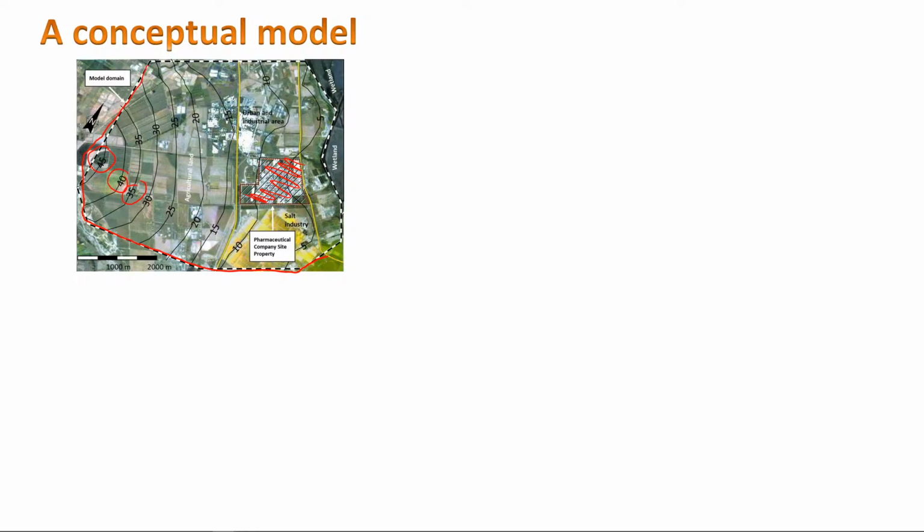So now you are expert in this. You know the flow direction is from high energy to low energy, so water will flow in this direction. You can almost trace it here. So water will flow here. Now you are expert in this, yeah? So this is not what my model is producing. This is what I'm observing in the field. These are the head values that I'm observing in the field, and this is what I want my model to reproduce.